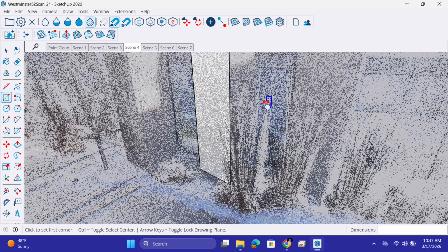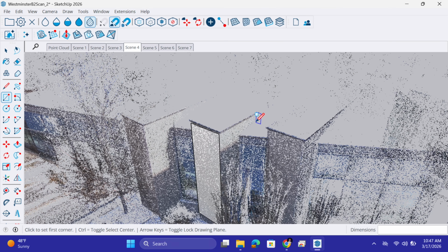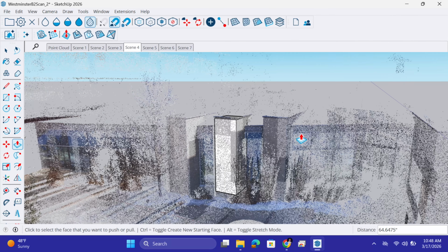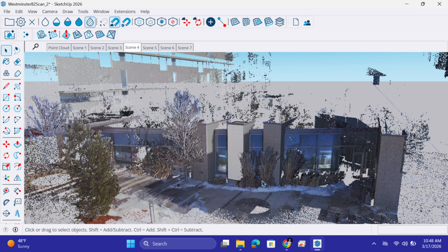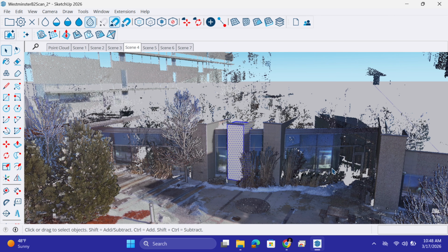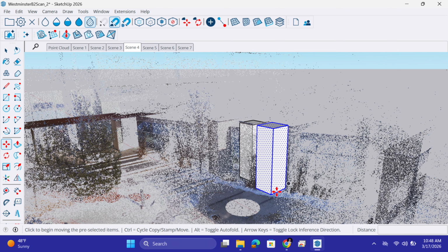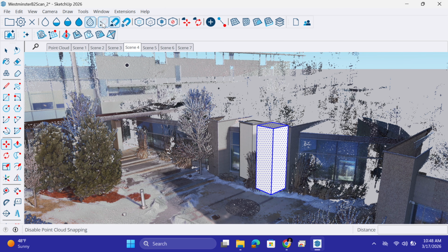And then, if I want to extend the depth of the column, you can do so, again, by using the same traditional tools in SketchUp that you may or may not be familiar with. And you can match the depth of the column in the real world structure. And everything is happening, like you're not setting your views or anything, you're not locked down to top or any kind of isometric views, you're just free flow editing, and now you're even copying and doing the second column without even worrying about any of that stuff. Exactly. You're just drawing what you're seeing.